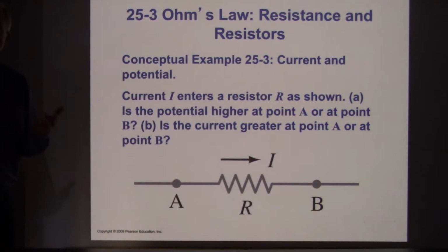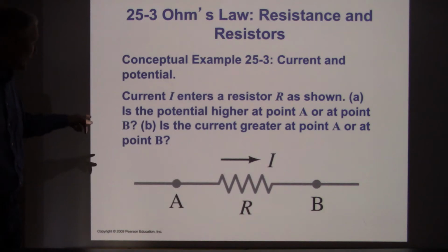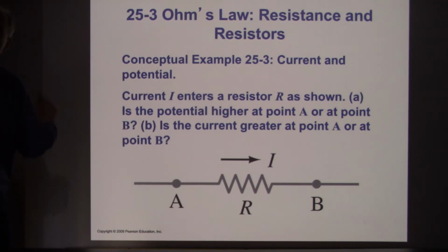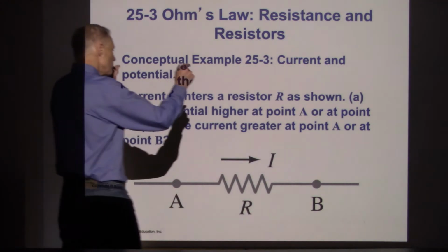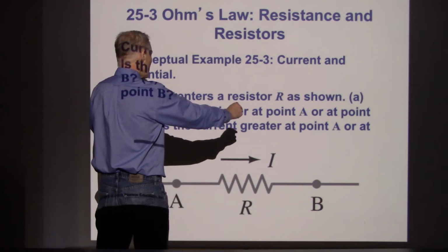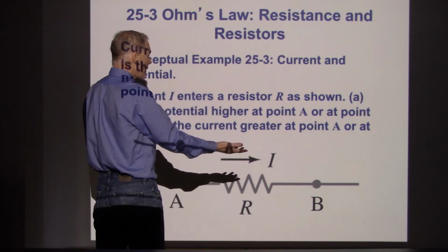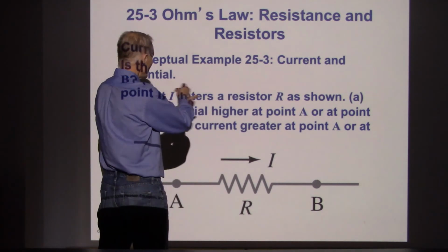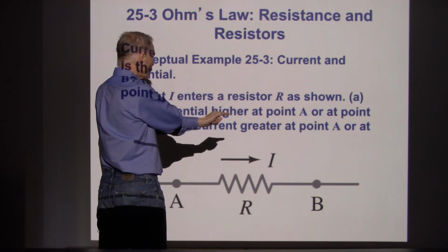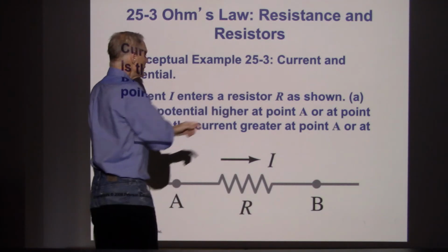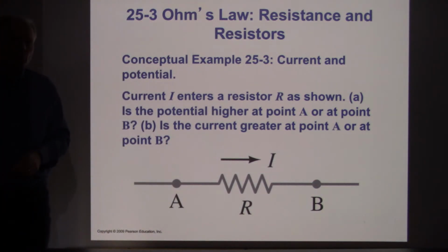So we'll say that there's a voltage drop, or a voltage across the resistor, and point A is going to be the higher voltage and point B is going to be the lower voltage. If I get a voltmeter out and I measure the voltage between A and B, and it reads positive 3.5 volts, if I take the leads from that voltmeter and reverse them, it will now say minus 3.5.